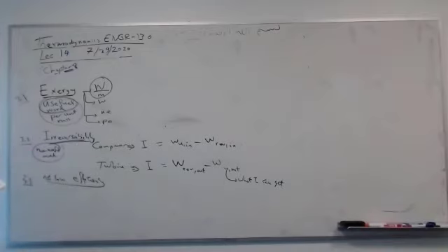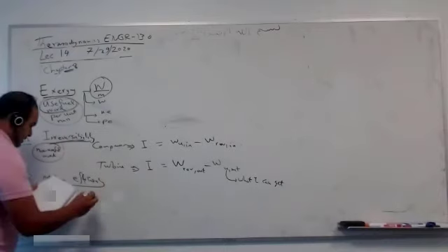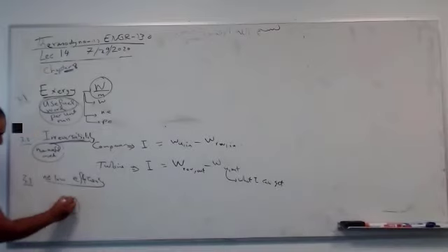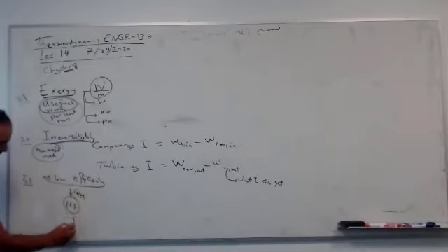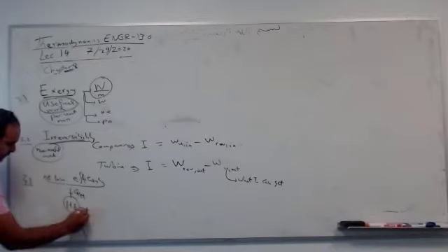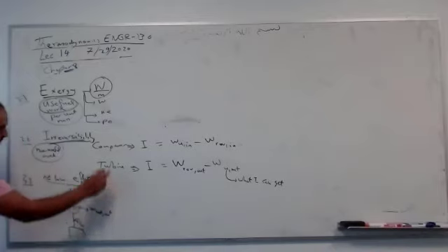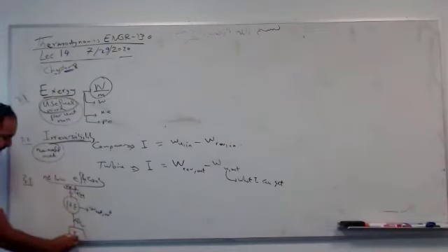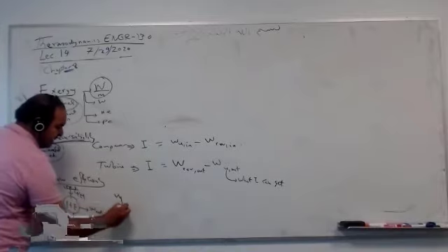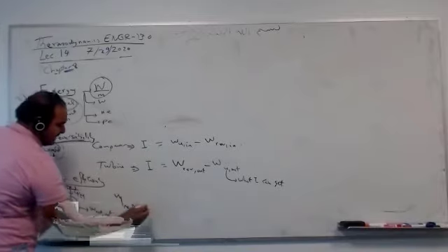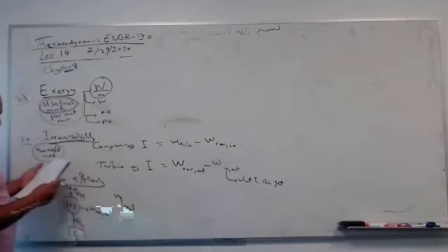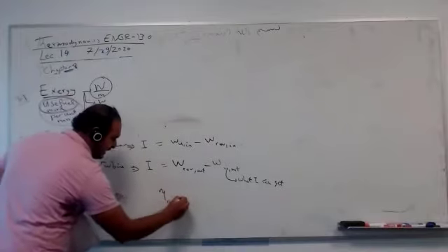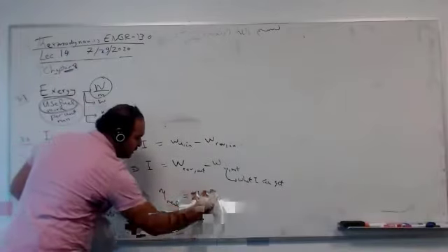Second law efficiency is exactly the same thing. Let's say you have a heat engine, with Q high, Q low, and W net out, between T high and T low. You have two efficiencies. What is eta real and what is eta ideal? Eta real equals 1 minus Q low over Q high, which is W out over Q high.